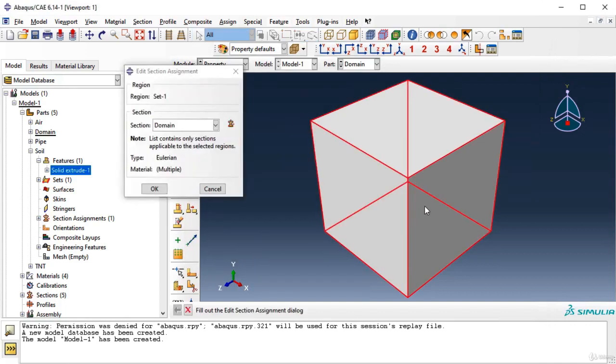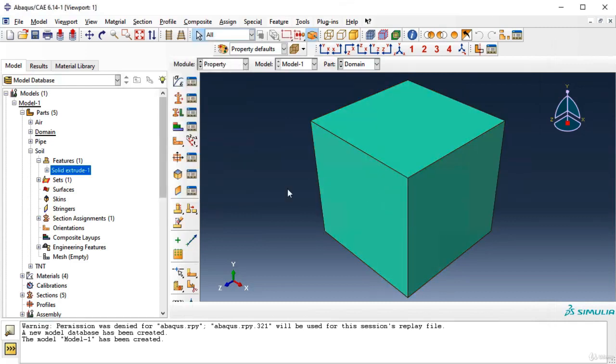And then assign this one to this model. So basically our Eulerian domain has all three materials, but the location of the material is not in the correct place. Okay, we're gonna do that, assign a material in a correct section in a load section, which is going to be the second part of this tutorial. Okay, so now we are done with the property.